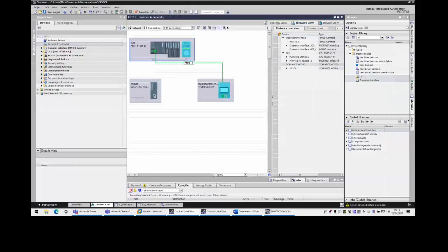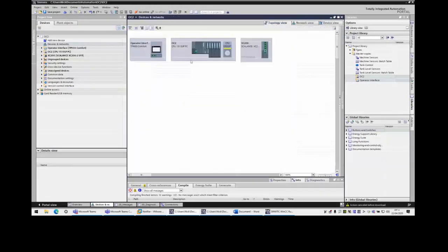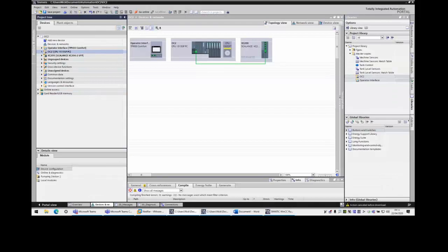we should be able to right click on here and go into our device configuration, and go into our topology view and join this port up to this port here. So utilizing the topology view, we can tell the controller how the point-to-point wiring is achieved in our system. So if we do have any breakdowns in the cabling, we can instantly see where the connections have been problematic for us. And this information will ripple across a number of the different platforms that we are going to look at. So what I'd also like to show you is in the settings of the controller itself.